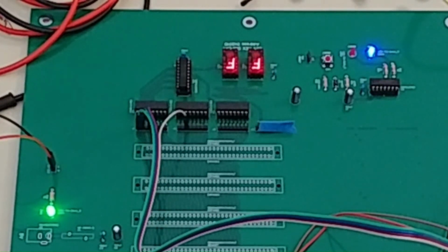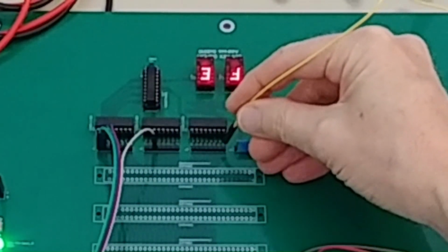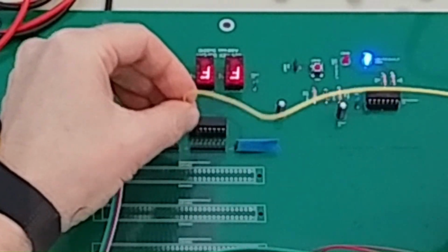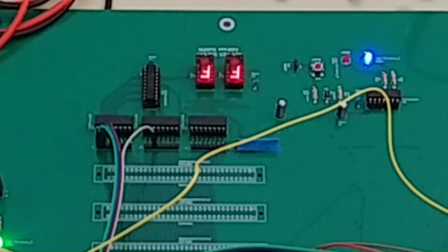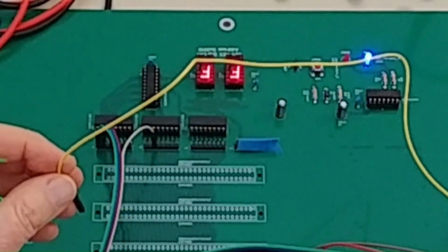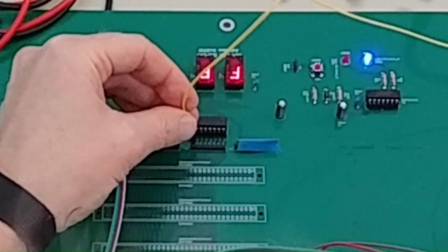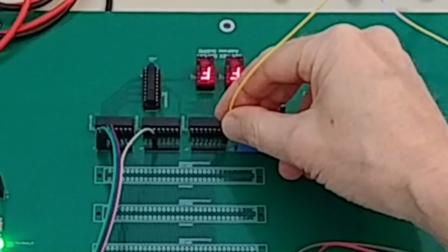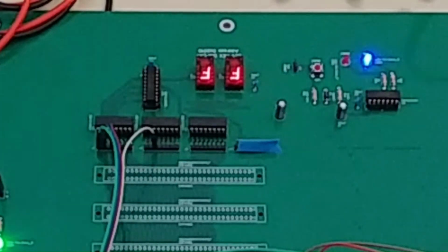Okay, so this is all working correctly. All right, so again, the U clock is asserted, and we can see that whatever's on the data bus, the hex display will load whatever's on the data bus. So let's take our write signal low. We unpatched our write signal, so this should not update the display, right? Because we require the address to match, and we require U clock to be high and the write signal to be high. So that's all behaving correctly.